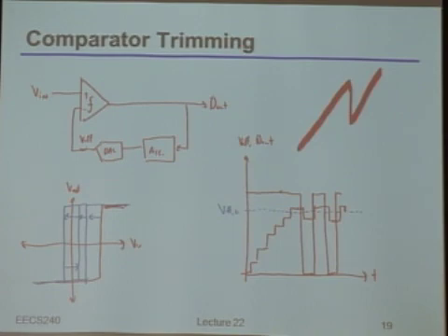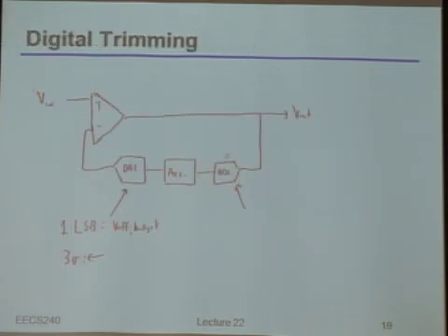Now, maybe just to quickly address one other thing, you could have been asking the question of, well, what happens if this ADC has offset? Or rather, more generally, let's say I use a comparator for this feedback thing, and I really want to zero out the offset of this amplifier. Meaning, I really want everything to go to 0, in terms of the remaining offset. Well, you guys tell me, is there a trick I can play, now that you know this, to actually make this whole thing go to 0 offset?